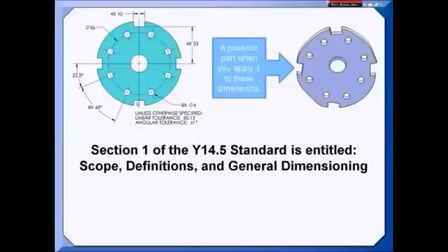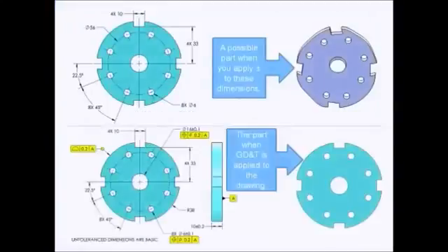It's sort of like the bullseye of a target, and then the tolerance is how much you can miss that bullseye by. That's like the size of the target around the bullseye. You have to, as you find later on in the standard, make the dimensions that locate features basic. So you notice I have an untoleranced dimensions or basic note down here. So the 16 and the 6 are not basic because they have tolerances written next to them, as does the 10. But the rest of these dimensions are basic. And then I have to apply feature control frames to control how much the part can deviate from these basic dimensions. Now the part you get will look a lot more like what you were intending to receive.